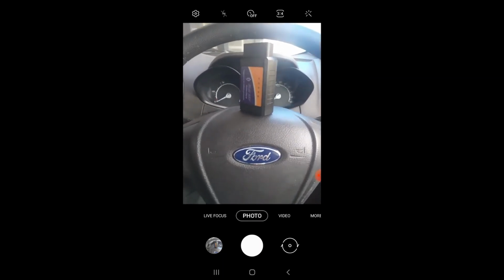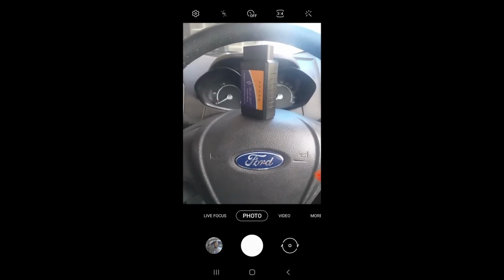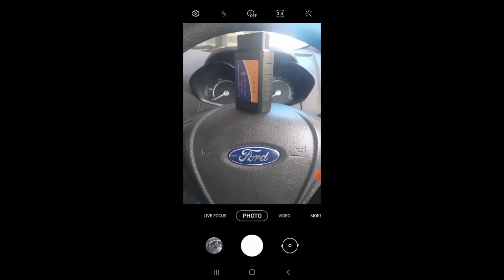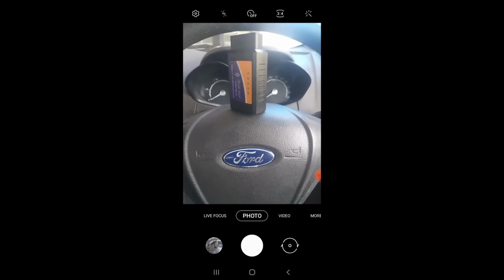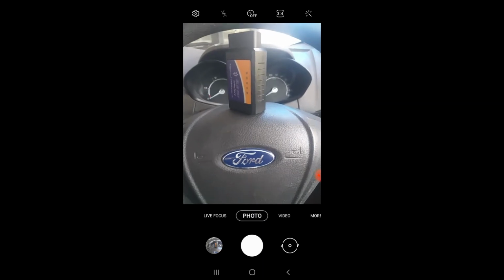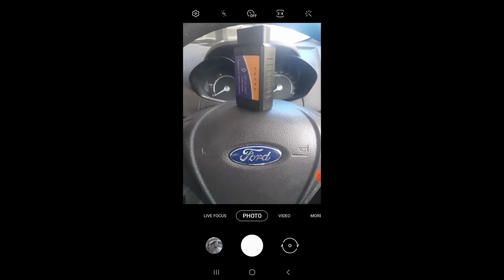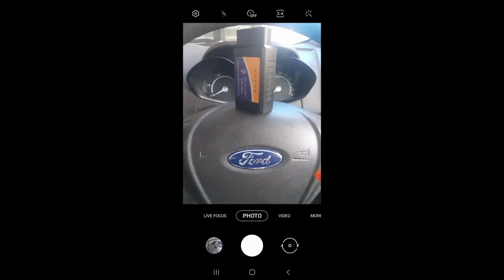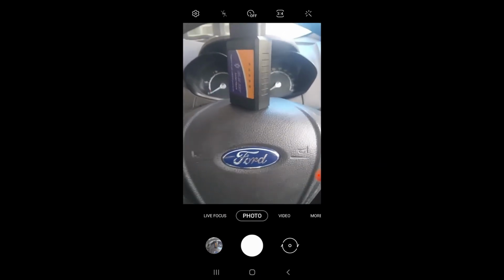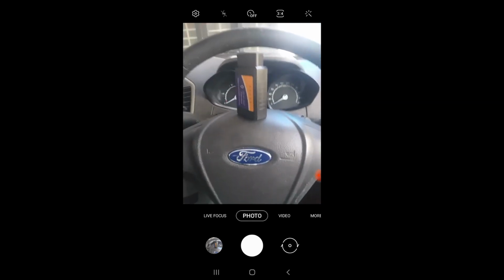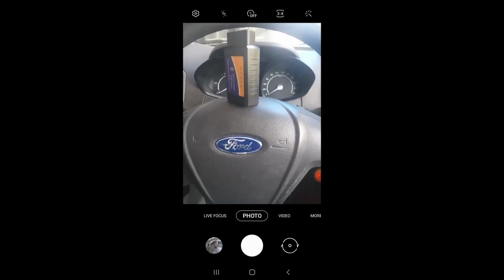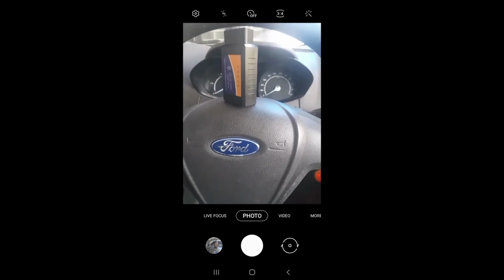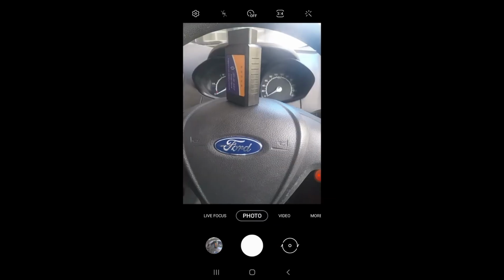And I'm using this scan tool to get the diagnostic trouble codes of this car. About trouble codes, there is a lot to say. Like if I say P0308, it's a trouble code. This code indicates a problem with certain functions, like it could be an injector or a fuel pump. So there are a lot of trouble codes, and we are trying to get those trouble codes.